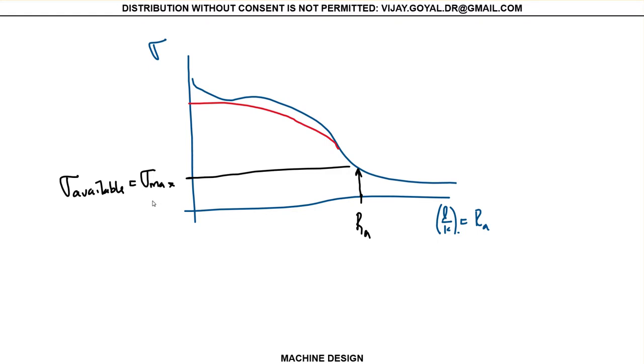Okay. Now, if by any chance, at any given point, you have a point that requires this amount of load level of stress, right? If it says this is what is required, you know that's not going to be possible at all. Why? Because I'm asking more than what my column can demand. Okay, so if you are exactly at this point right here, your factor of safety is going to equal 1. You will be at the onset of failure.